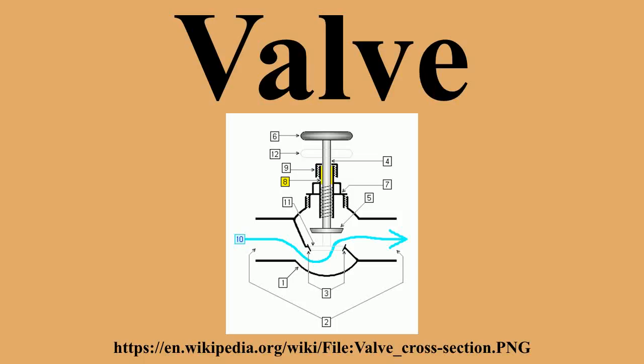Disc. A disc valve member is a movable obstruction inside the stationary body that adjustably restricts flow through the valve. Although traditionally disc-shaped, discs come in various shapes. Depending on the type of valve, a disc can move linearly inside a valve, or rotate on the stem, or rotate on a hinged trunnion. A ball is a round valve member with one or more paths between ports passing through it. By rotating the ball, flow can be directed between different ports.